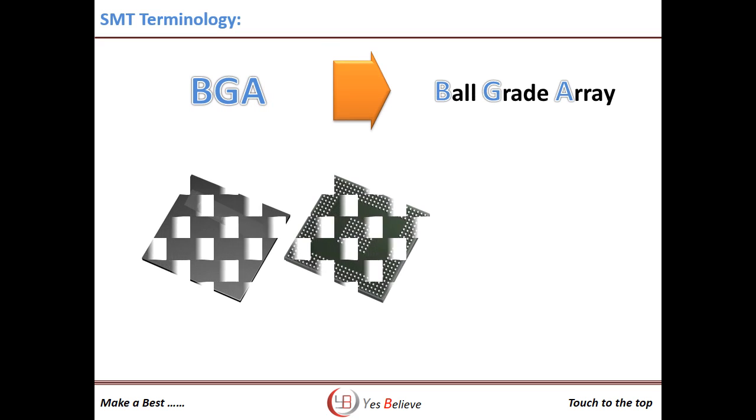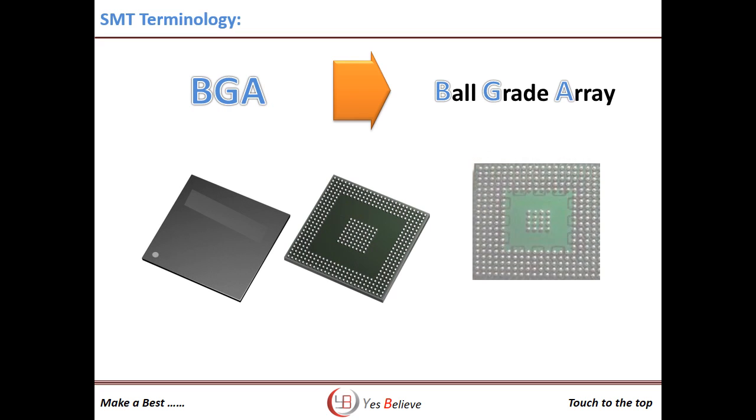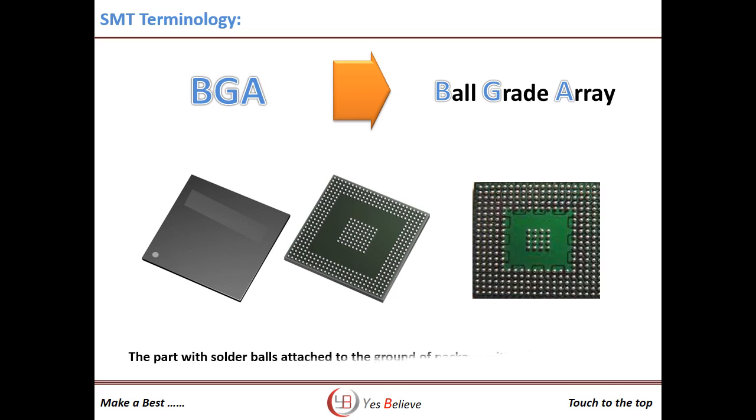Next is BGA. The full form of BGA is ball grid array. It is one of the large-scale integrated circuit packages. An LSI bare chip is mounted on a small printed circuit board. Behind the PCB, two-dimensional arrays of hemispherical terminal balls are arranged. The other SMT components like QFP, QFJ, SOP, SOJ, etc. are explained in the SMT Material chapter.